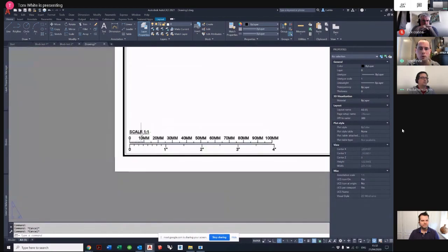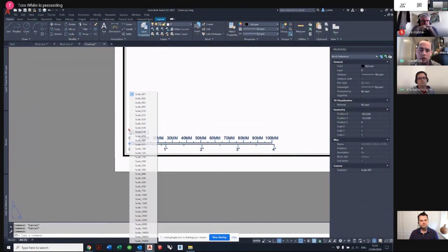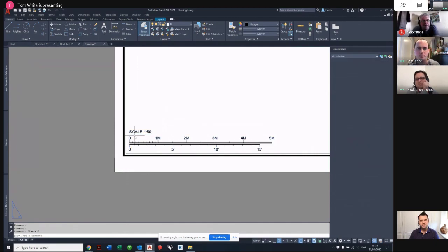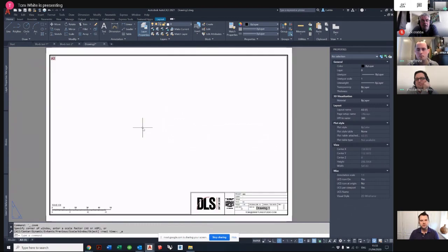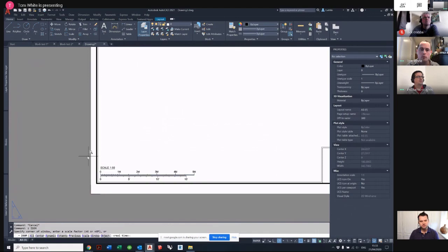But what's going to help you even more is this as a scale bar, which has the attribute in this circumstance of visual states. So you're visually showing different scales, but essentially it's as simple as a different piece of paper. So there's a scale of 1 to 2, or there's a scale of 1 to 50, and basically all it is, it's just showing a different block. So it's called a visibility state, I believe. And so, all together, those are called dynamic blocks. Is that right? So you're creating these different ways of using the same block, but dynamically to provide different information.